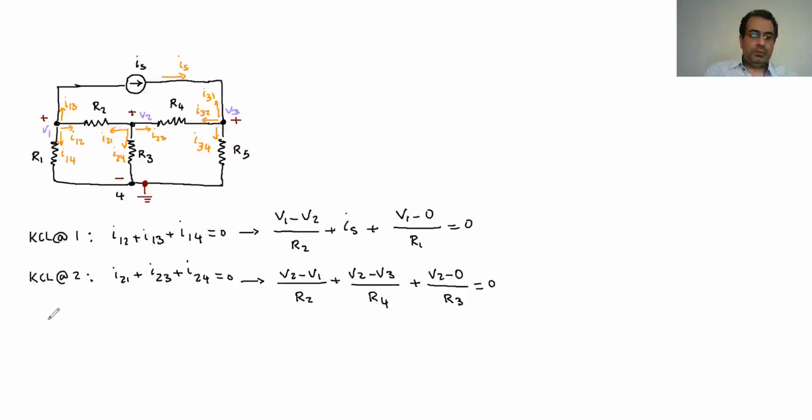And then we come to the third point. This is going to be the KCL at 3. Again, we add all the currents at that node and it should come to 0. So I3,1 plus I going from 3 toward 2 plus I going from 3 toward 4 should be 0. Look at the I going from 3 to 1, the I3,1.